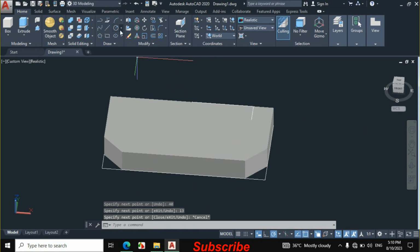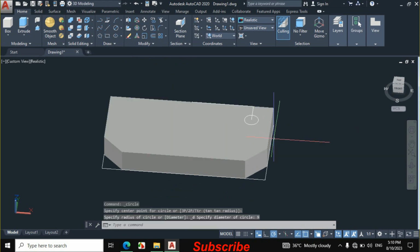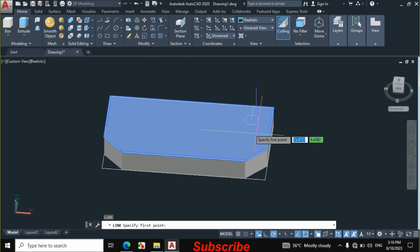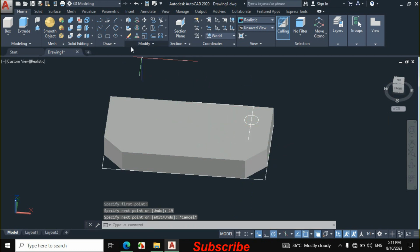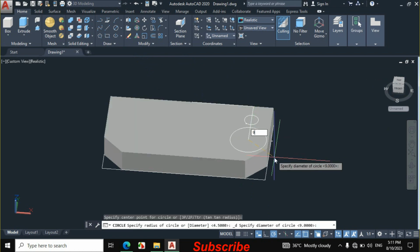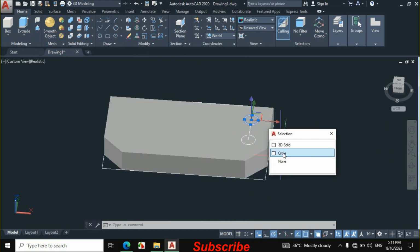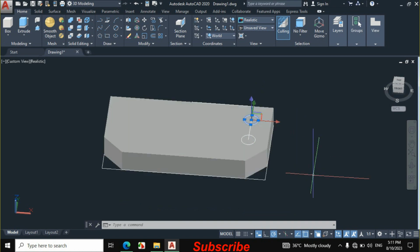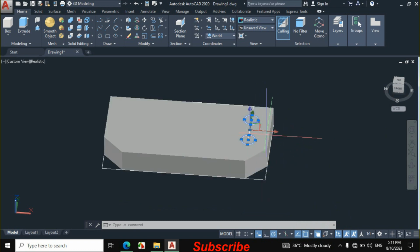Then draw a circle, click on circle, center diameter, and draw a circle of 9 mm diameter. Again enter line from the keyboard, then click on the center point of the circle, and make a straight line of 19 mm, enter, then escape. Click on circle, then again make a circle of 9 mm diameter, then select this circle. So the circle is selected very easily because of this option, selection cycling. Then again click on circle, select circle. So the circle is selected.